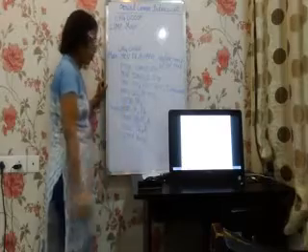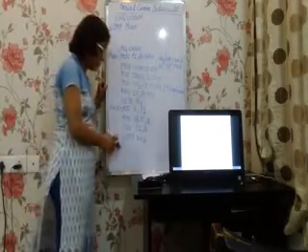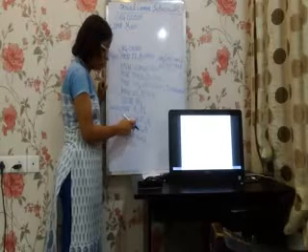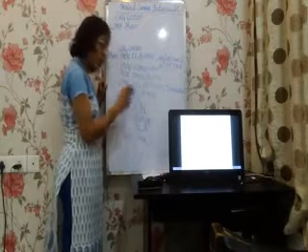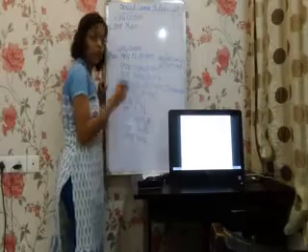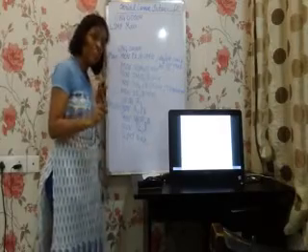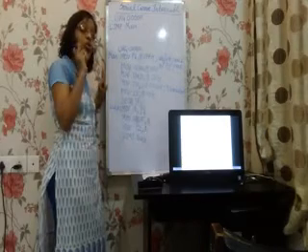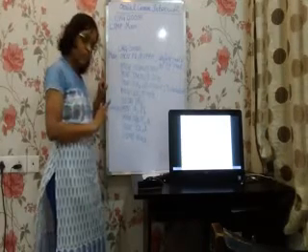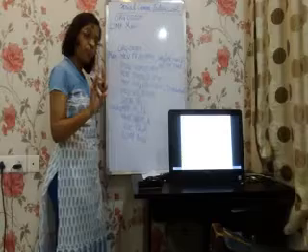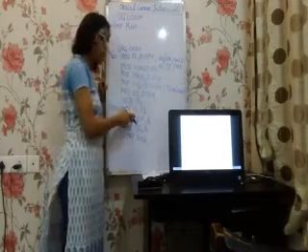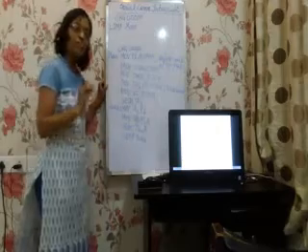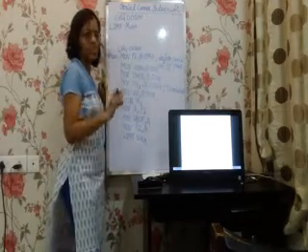I have to take the data from port 1 and send it to port 2 via the accumulator. Also give a copy to the SBUF register, because it is mentioned in the problem statement to give a copy of the data from port 1 to the serial communication port. How will you send the data to the serial communication port? By putting it into the SBUF register. This is my main program. Now my subprogram is given only 8 locations, 23 to 2F.